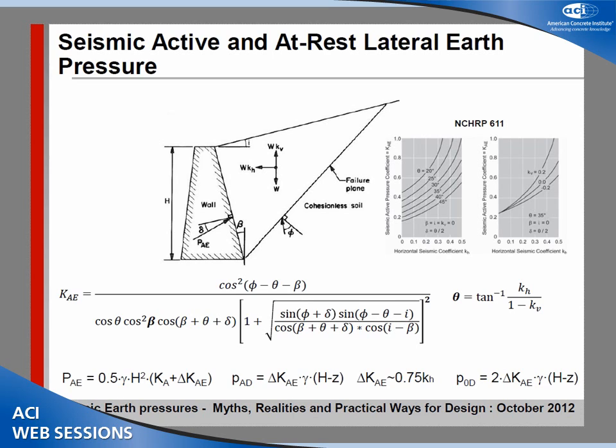For calculating the dynamic soil pressures, there is not really a guideline, but one of the methods that is widely used is Mononobe-Okabe, although this method is in theory for calculating active seismic earth pressures. There is a lot of discussion that it is so conservative that actually you could use it even if the structure is really at rest, and then the equation, although it may look a little bit complicated, can be simplified.